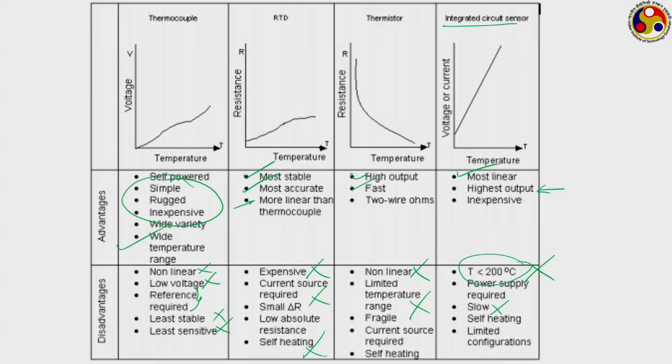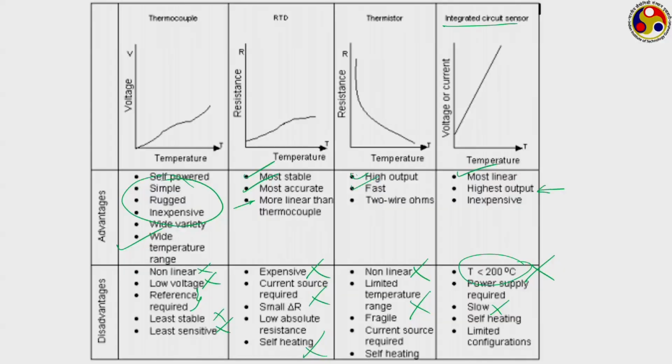Thermocouples can cover a very high operating temperature zone. So, if you are looking for applications which are quite rough and you have a large temperature span and you want to measure temperature at several points, thermocouples are ideal compared to RTDs. And if we specifically need a very linear output at low cost, then IC based sensors or bulk junction semiconductor sensors probably are the better option.